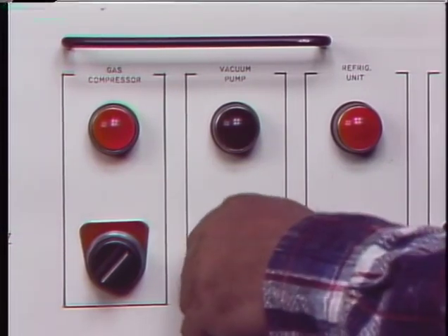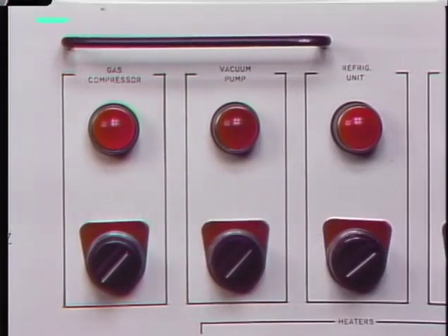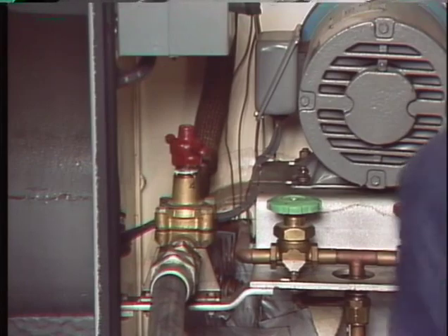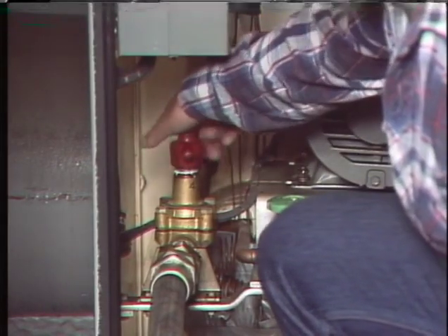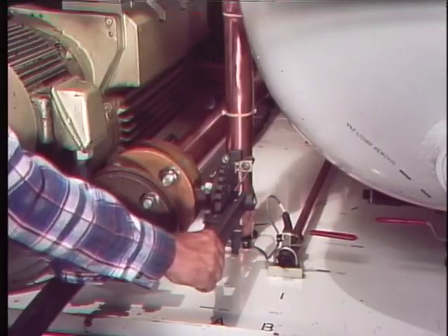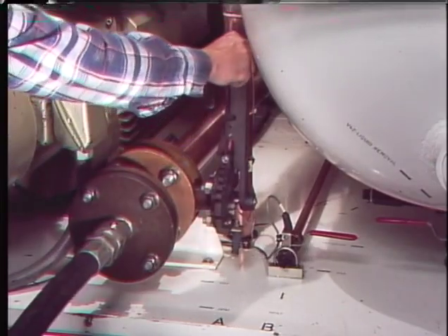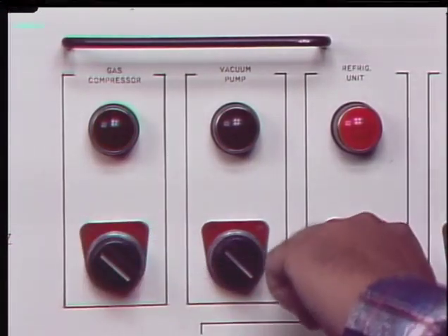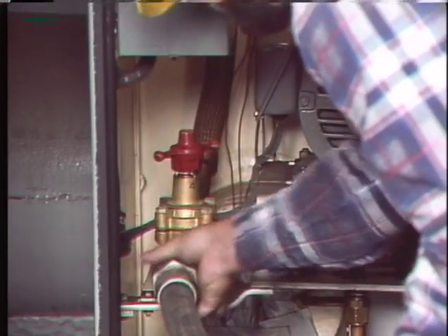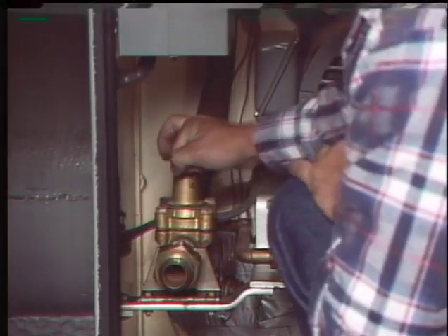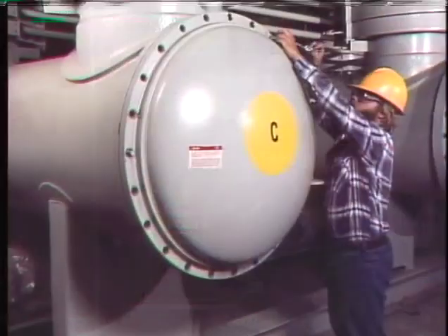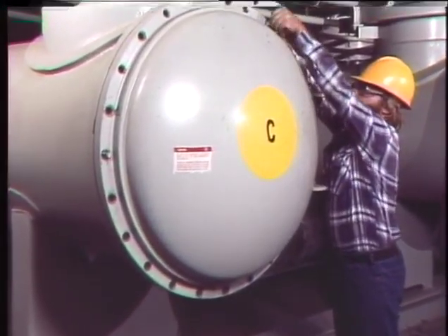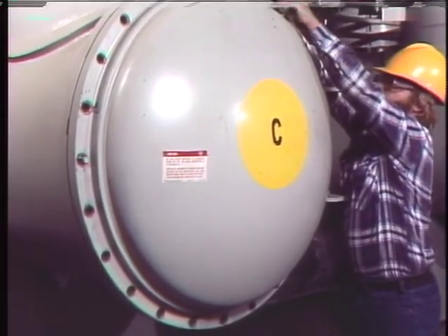Then the vacuum pump is restarted to draw a vacuum in the breaker, ensuring that all the gas is removed. After the proper vacuum is drawn, the main tank cutoff valve is closed. Then the inlet valve at the trailer is closed, and the vacuum pump, compressor, and refrigeration unit are turned off. The hose is removed from the gas service connection, and the main tank cutoff valve is opened to allow air into the breaker. Then the inspection doors are unbolted and opened at each end of the breaker.